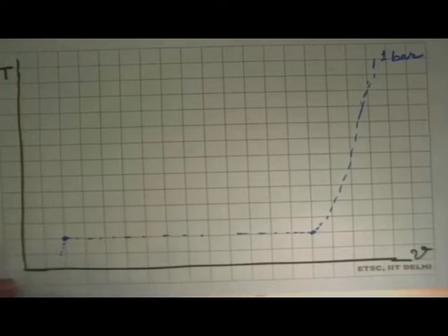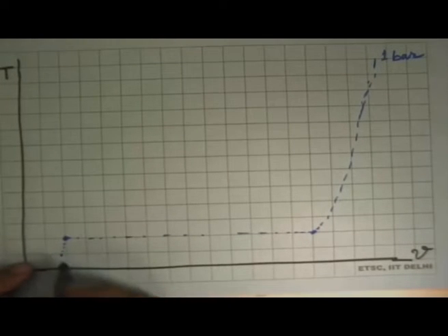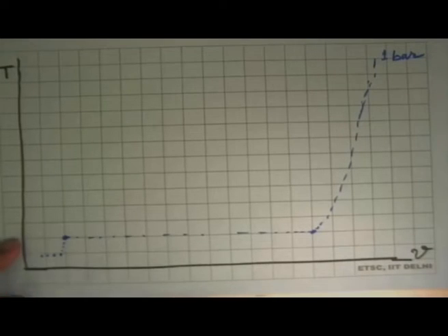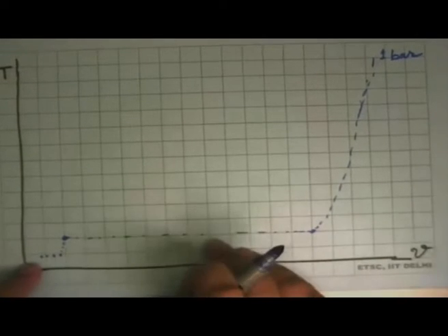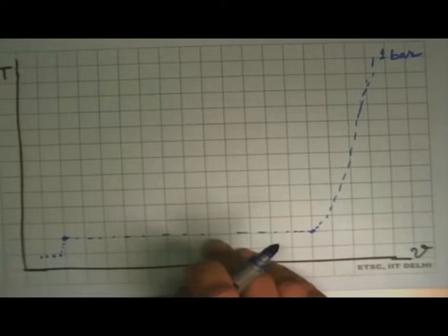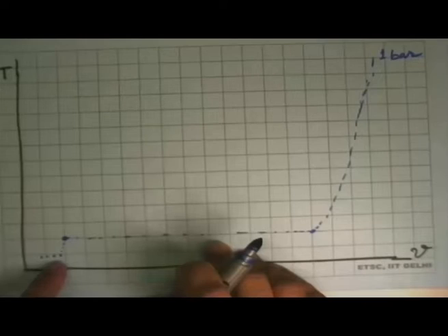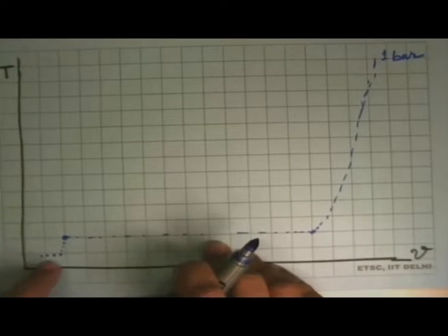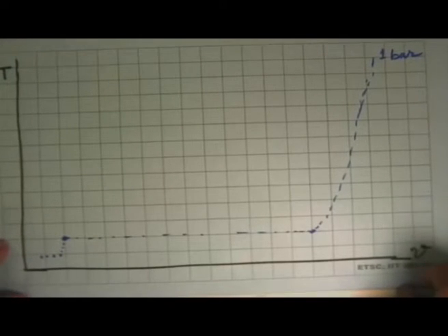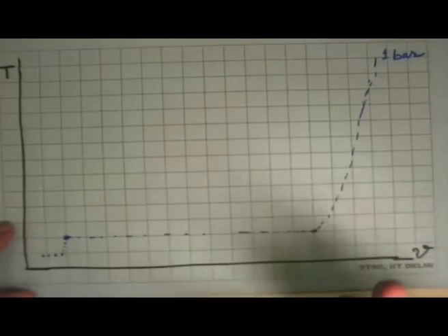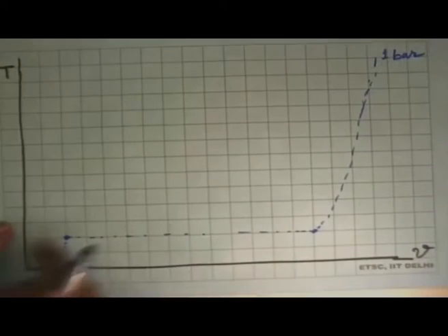Now what will happen if we do it at 10 bar? Let's say I start from the same temperature, 40 degrees Celsius, and increase the pressure to 10 bar, 20 bar or something like that. Those states will go this way. I am exaggerating a lot, but in reality the change of volume of a liquid is very, very small. You can see in the plots, there's practically no difference between these densities. But just to illustrate the point, I have pulled them out. In reality, they are not that far off. The simple reason is, in school we have learned liquids are incompressible. That's the manifestation here.